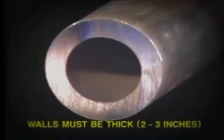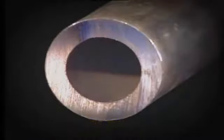In order to withstand this high pressure, the walls of the pipework must be thick, perhaps 2 to 3 inches, depending upon the pipe diameter. The steel alloy materials containing chrome and molybdenum are selected to withstand the stresses imposed by the high temperature operation. A thick layer of heat insulation is placed around the pipe to prevent heat loss to atmosphere.